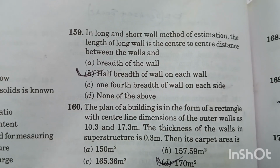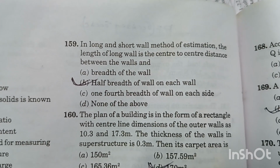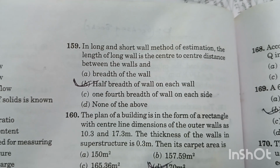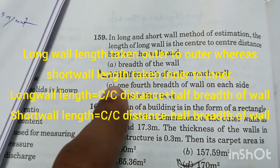Question number 159. In long and short wall method of estimation, the length of long wall is the center to center distance between the wall, plus half breadth of wall on each side. Option B is the right answer.